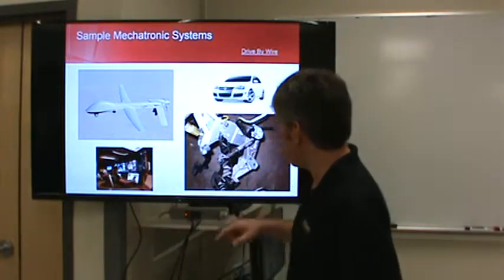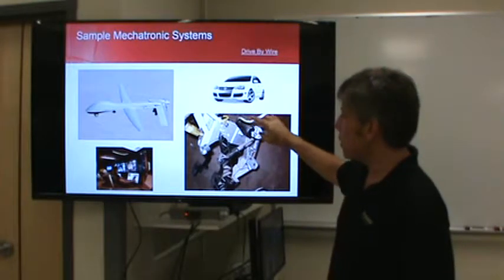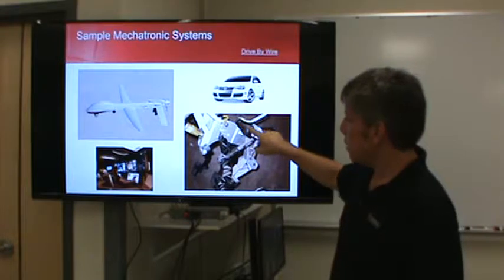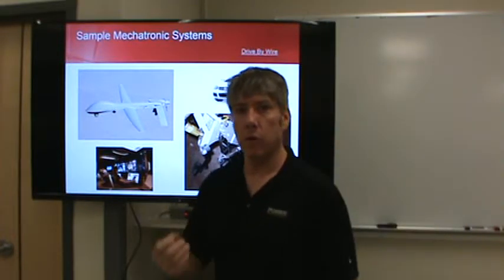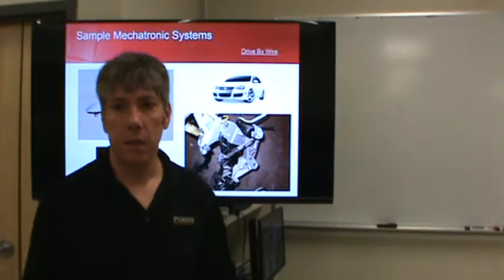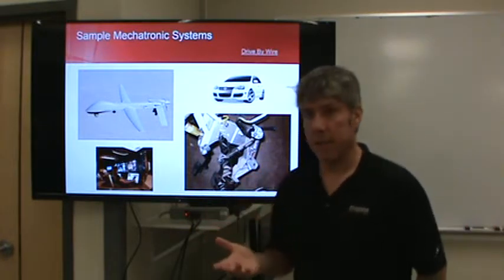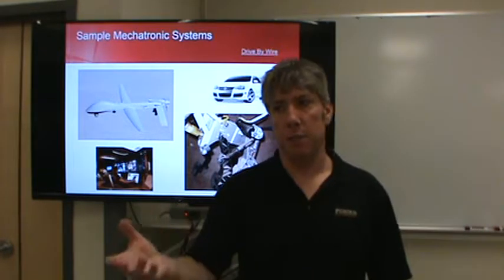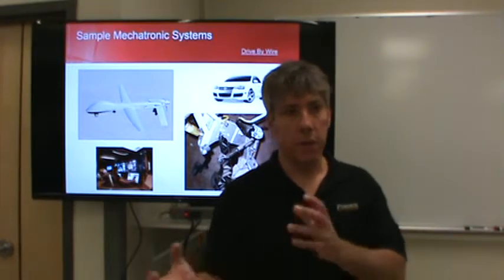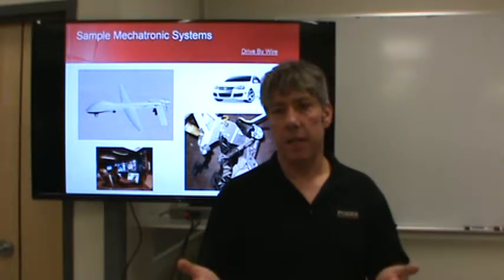So basically the way it works is the gas pedal moves a rotating sensor. It's not just a variable resistor, but you can think of it as that, a potentiometer, and that sensor sends a signal to the computer requesting essentially an amount of power output or an amount of speed, okay? Or a throttle position is the way you can think of it. There's no throttle in my car. In reality, there's an injector pump, and there is a throttle that controls airflow, but the two things work together so that you hopefully maintain efficiency. Okay?